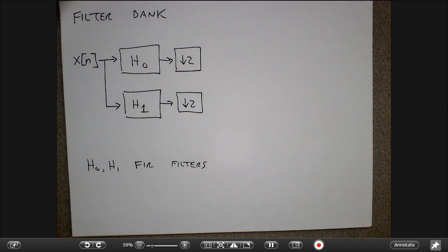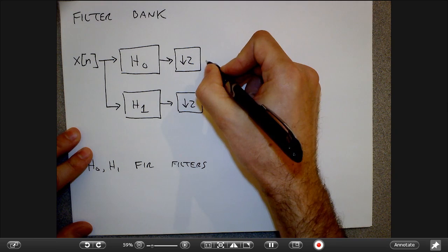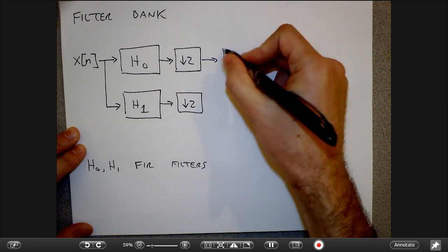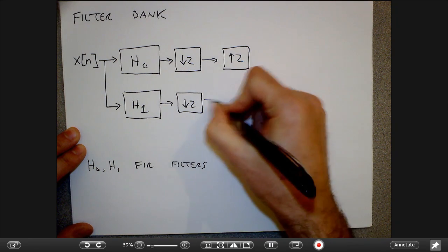And so that's a way to represent the signal. I had n numbers before, now I have n different numbers coming out, right? So again, you can think about what's happening inside this filter bank as changing the basis of the function, okay? And if I want to reconstruct the original function, if I want to switch my basis back to the original time domain, then what I would do is fill in some zeros here.